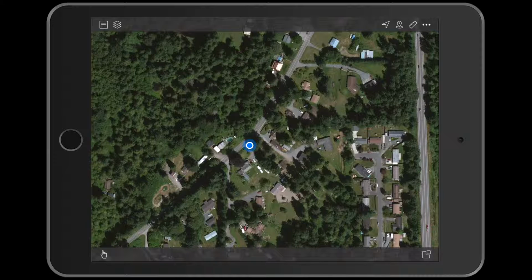There are two methods of drawing in Apex, manual and GPS track. With the manual method, you place points over the map as desired to create your drawings. Points may be edited, that is, moved, deleted, and inserted, both during creation of your drawing and after you have saved it. GPS track-based drawing operates like a recorder. You start the tracking, pause and restart as needed, and save when done. You may not edit points during GPS track drawing creation. You may edit a saved GPS track drawing.